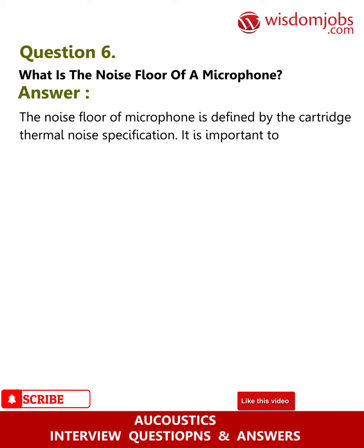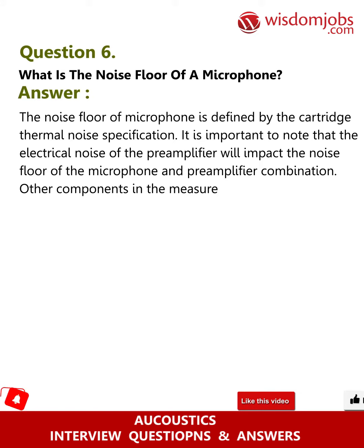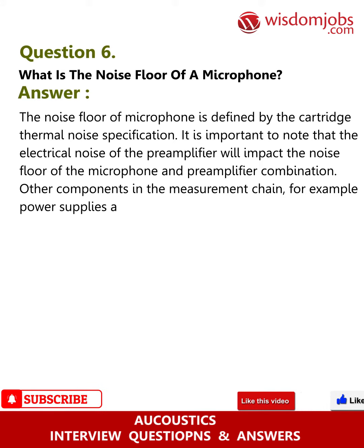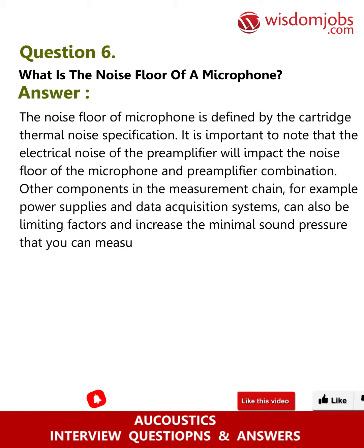It is important to note that the electrical noise of the preamplifier will impact the noise floor of the microphone and preamplifier combination. Other components in the measurement chain, for example power supplies and data acquisition systems, can also be limiting factors and increase the minimal sound pressure that you can measure.